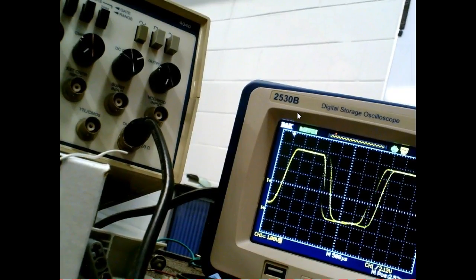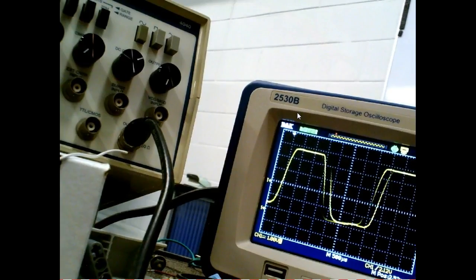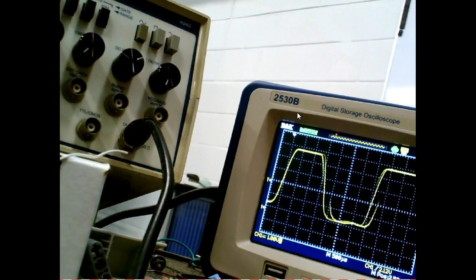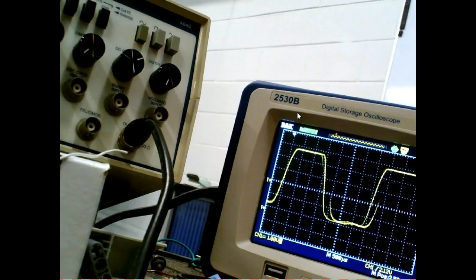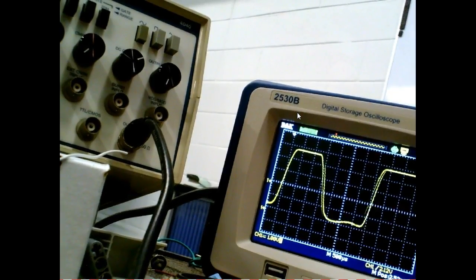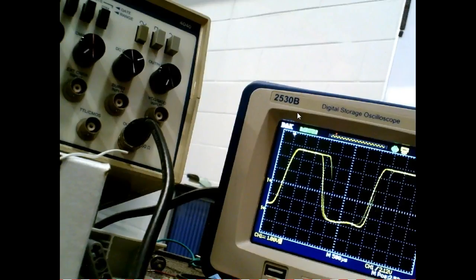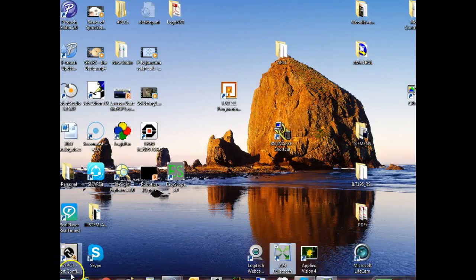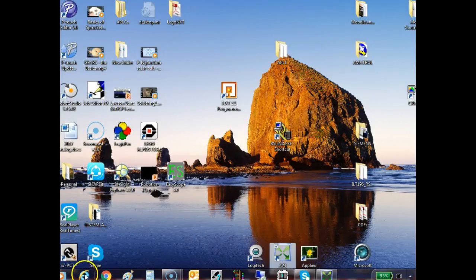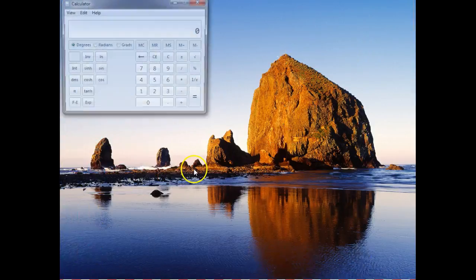First of all, I have eight slots in this encoder. So that means for every revolution, I'm getting 8 of these things. Right? You understand? So I want the time for one revolution. So if this is the time it takes for one of them, how long is it going to take for 8 of them? So what would be the first thing I would do? I would multiply by 8. You can multiply the time or you can multiply the frequency. It doesn't make any difference whichever way you want to do it.